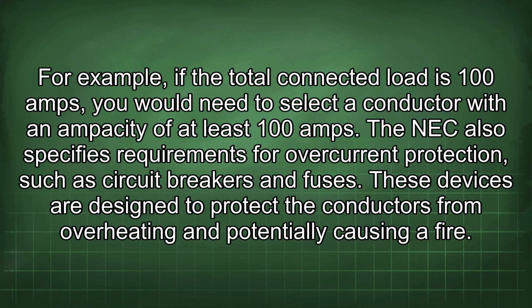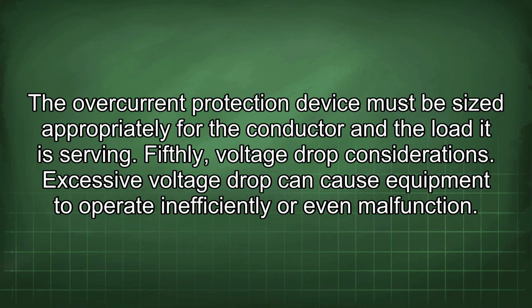The NEC also specifies requirements for overcurrent protection, such as circuit breakers and fuses. These devices are designed to protect the conductors from overheating and potentially causing a fire. The overcurrent protection device must be sized appropriately for the conductor and the load it is serving.